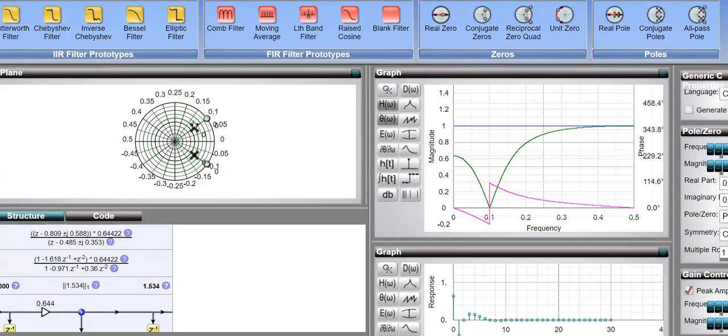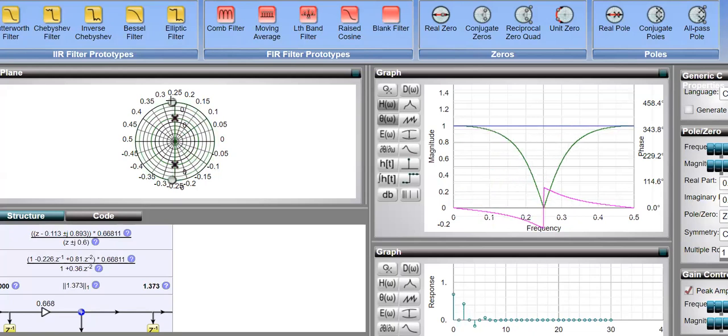So you need to change both the pole locations and the zero locations for this purpose. However, you can change only the pole or the zero location. That will definitely change the notch frequency, where you are targeting your notch frequency. It definitely depends on the zero location. I believe you can understand now how they are operating in the magnitude response and the phase response.